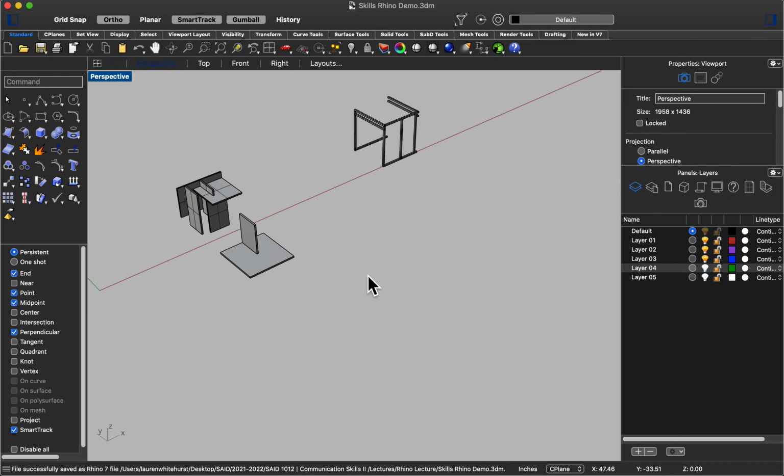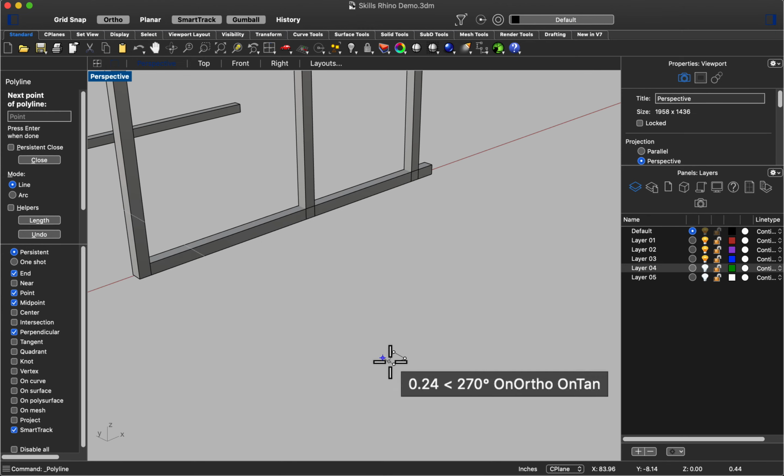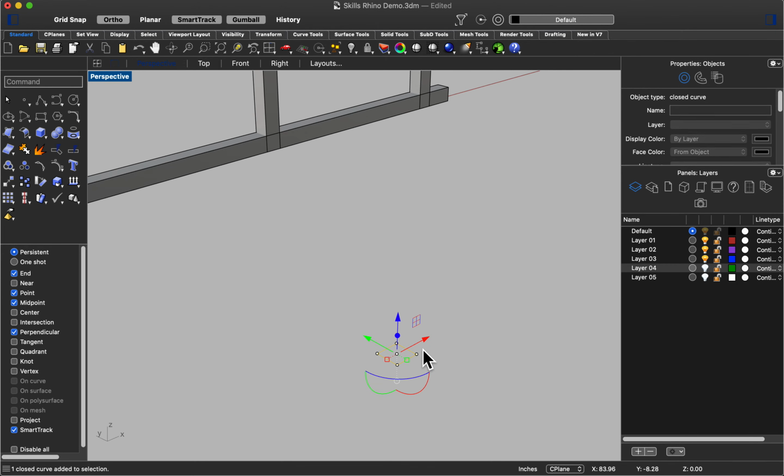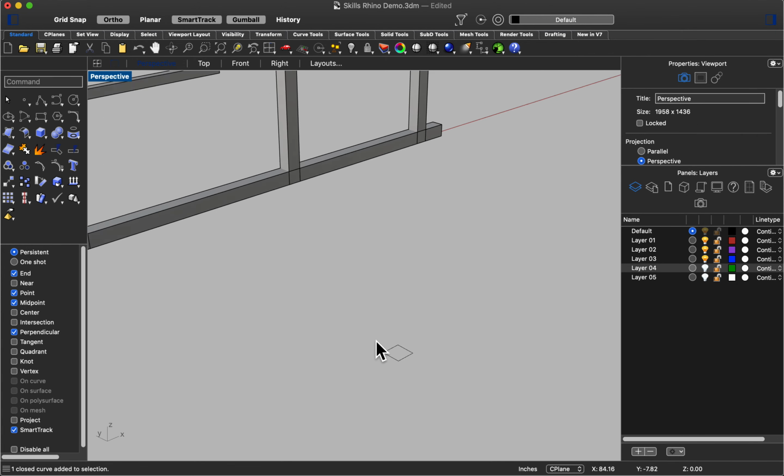So I made the line cubes in a similar way, where I first drew out a square. In this case, I'm just going to do 3/8. Let's say that's what it was in the final. I think it was 3/8 of an inch. So 3/8, and I click, and then I do 3/8, and I click, and then do it again, 3/8, and then zoom in, select that point. Now I have that same thing where I have a curve, and I'm going to extrude it by typing extrude curve. Now I'm going to extrude it 12 inches again. And so now I have this line.